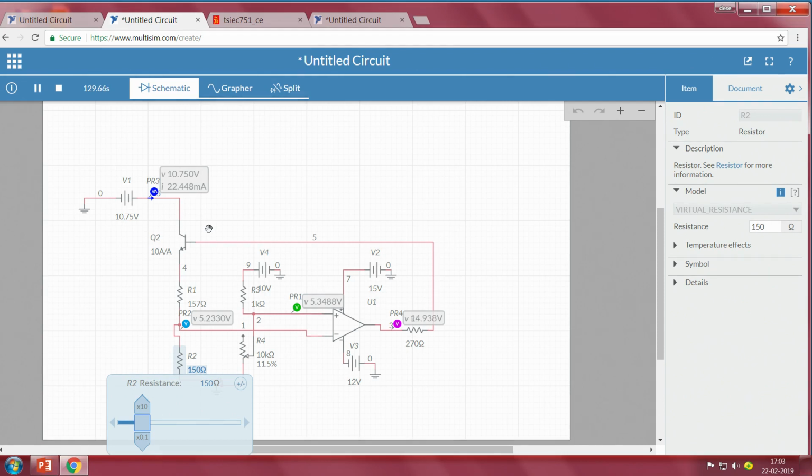Assuming there is some amount of airflow, because of airflow there is a change in the heat flux, that is, the temperature across the resistor drops, there is a change in resistance and accordingly you have the drop, and then the feedback mechanism works, drives additional current, self heating happens and the circuit regains its balance.